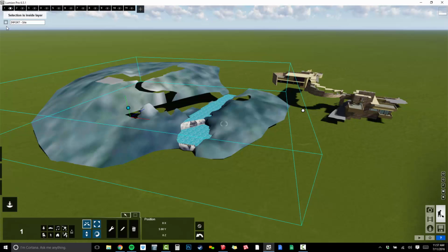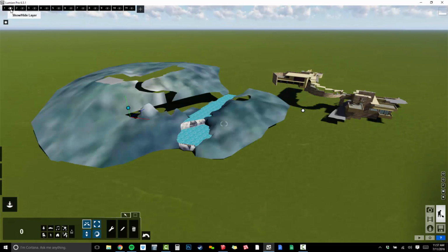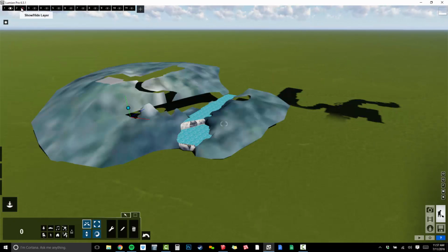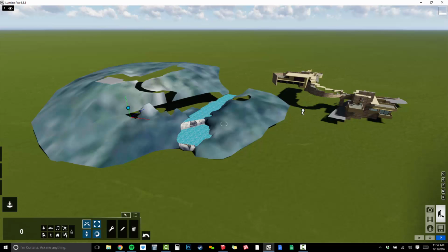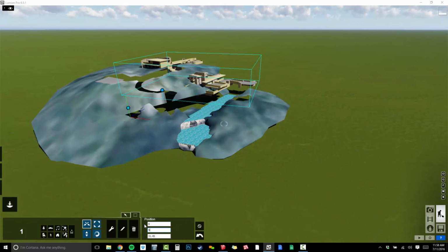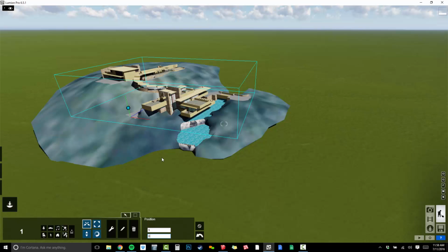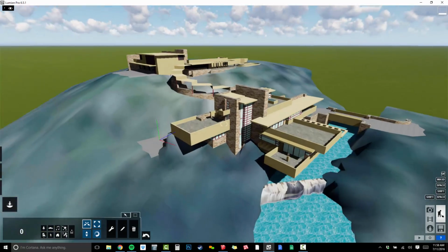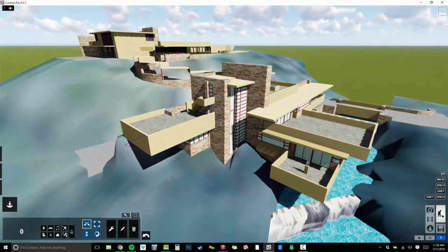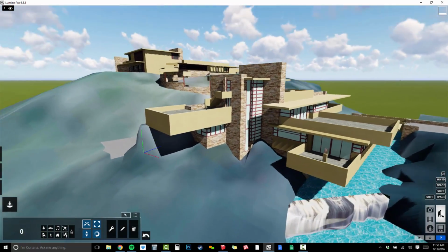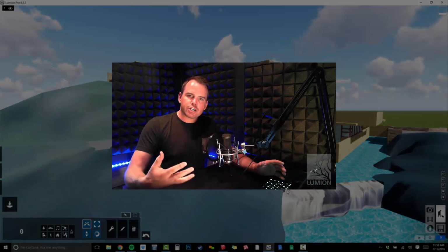So I'm just going to click there, and now my site is controlled by my site layer, and my Building A is controlled there. Now, if I click on this node here to select Building A, I can move that node to 0, 5, tab, backspace, and then 0. So when that's on 0, 5, 0, and then deselect, that's going to sit right where it needs to be, synced up and meshed with that site.